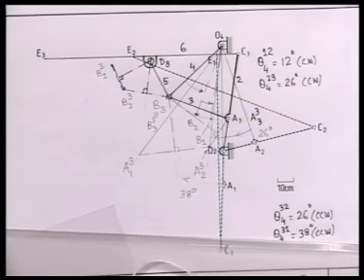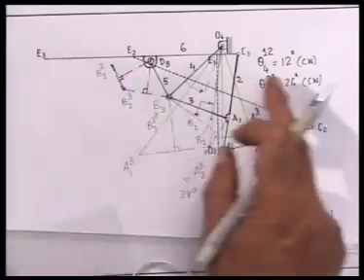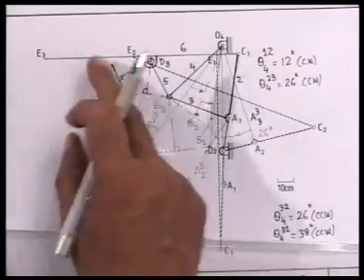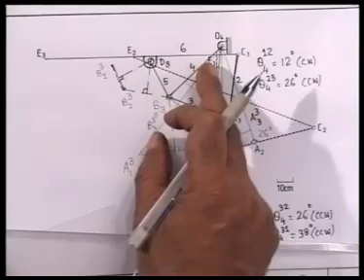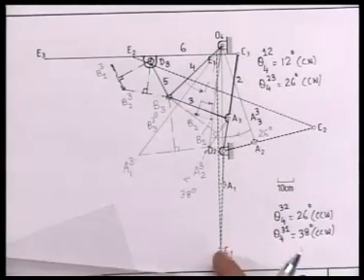So again we have used the multi-stage synthesis procedure to design the 6-link rail-less garage door mechanism, where the garage door has the desired movement, that is almost horizontal movement inside the garage, then drooping down fast to take up this vertical closed position. So we have seen how the 3-position synthesis technique for function generation, motion generation and path generation can be applied at various stages to even design more complicated mechanisms.